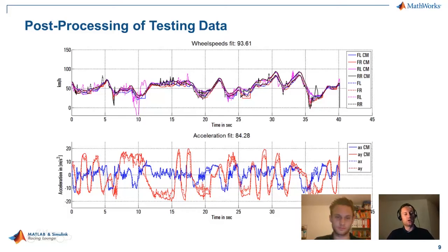Either you have very high longitudinal or very high lateral. Could I see what kind of track that is, based just on the accelerations? Yeah, sure. If you take a look at the accelerations at the beginning of the track, you can see that the car is performing a slalom because of the switching of the lateral accelerations from minus to plus and minus to plus. Okay. And again, the correlation between modeled results and actually tested results is pretty good for the accelerations.